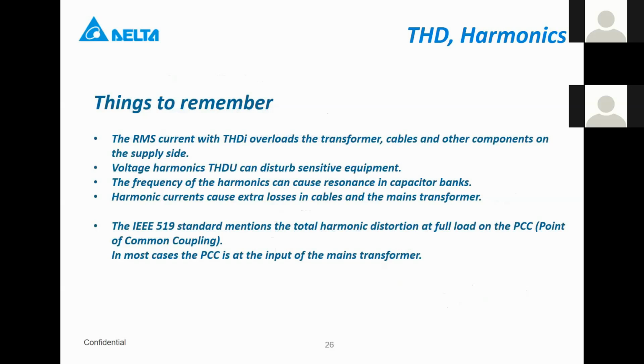Things to remember: THDI currents, harmonic distortion currents, can overload the transformer, cables, and other components on the supply side. Voltage harmonic distortions can disturb sensitive equipment.